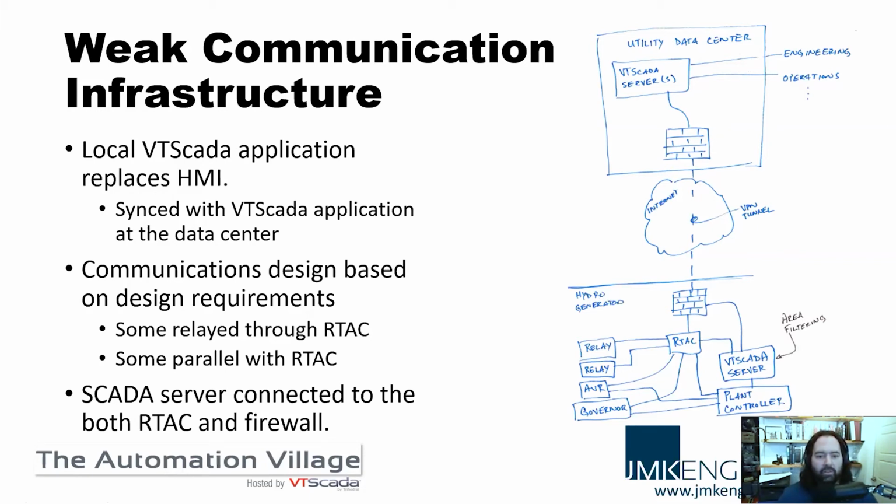One of the advantages of this hierarchy is that at all of their generation stations, where they have a lot of moving parts, they have a full-blown HMI SCADA server right there on site that allows them to back everything up. If there's ever a breakdown in communication between these two firewalls, all that data stays backed up. And finally, the operators can use that SCADA server just like any other SCADA server and have operator notebooks, historians, logging, etc.